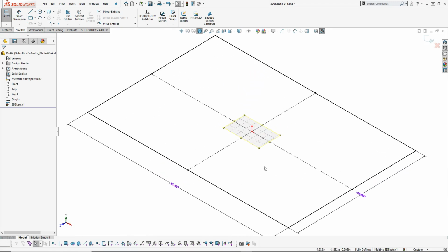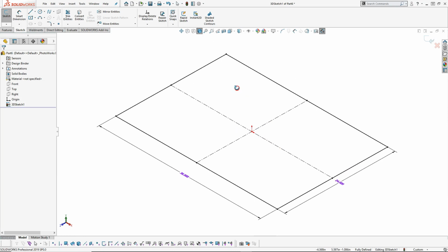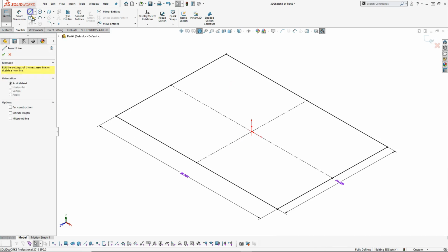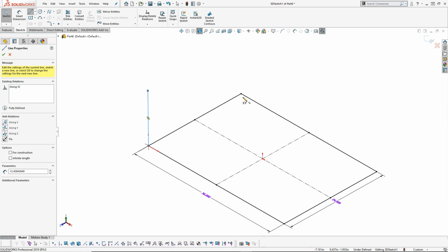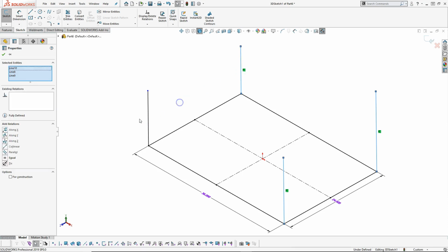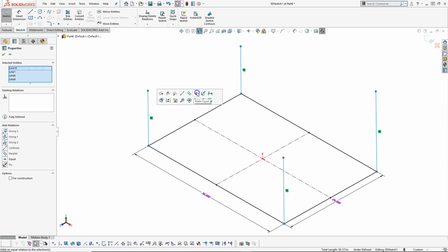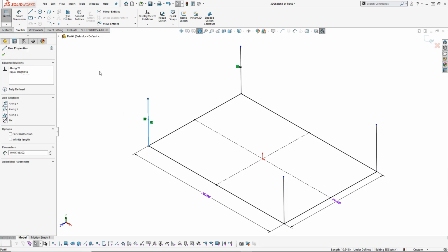So that's going to keep everything that I draw in this plane until I double click. Once I double click, now we have that same type of situation where I can draw in the direction of the arrows, and because I have connection points that aren't going to rotate away from me, hopefully I can go to the corners and just snap to those locations and draw my lengths. All of these, to make it a little easier, if I select, Control Select, and one more Control Select, I can set to equal. And because of the direction that I pulled it, they're all going to be along Y.